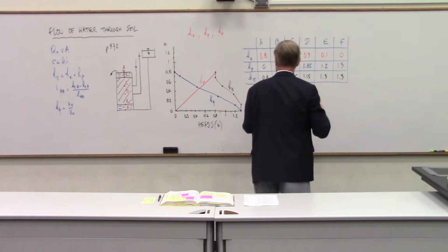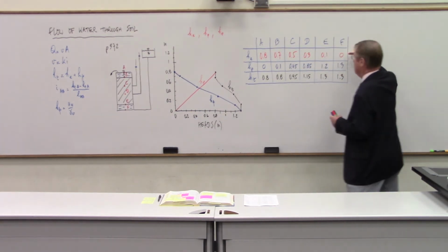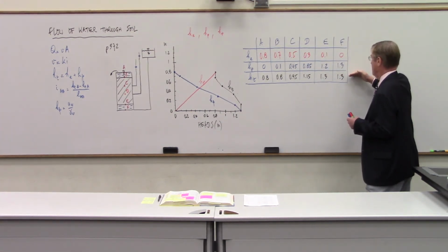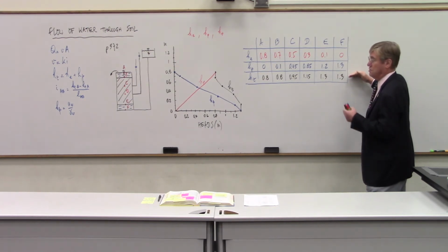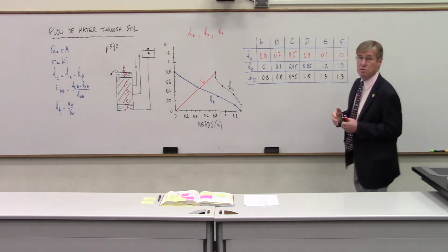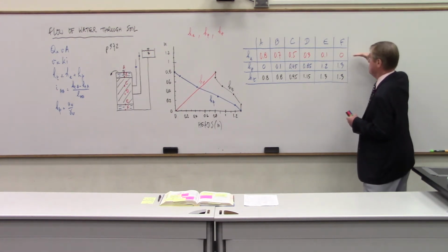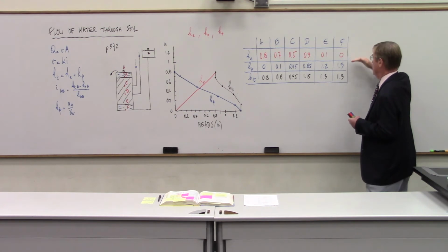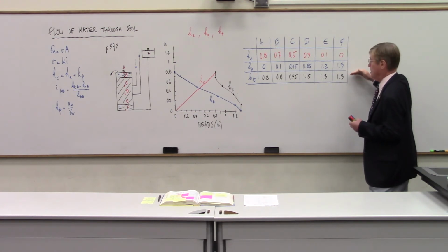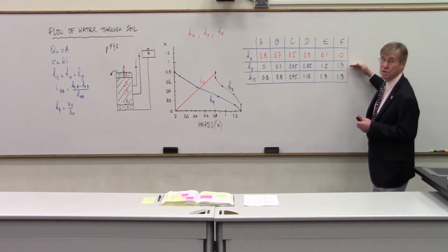In this case we went elevation head, pressure head, and total head. But in the general case, when we deal with those three-dimensional problems, we will go elevation head, total head, and then by difference we will get the pressure head.